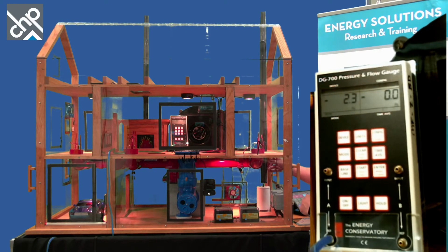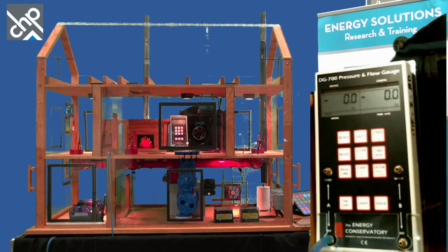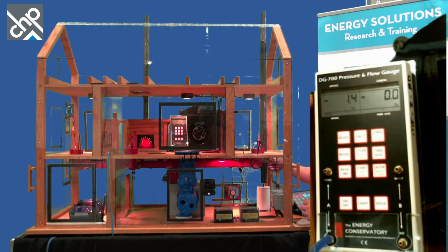Now I'm going to do it with the fireplace. I didn't have the fireplace on, but let's turn the fireplace on, and you'll be able to see these pressures from the smoke going up the chimney. So let's see what happens here. You see that the smoke is going up the chimney at this point, and I'm going to make that supply leak. We noticed it made a negative pressure, and we'll see if it affects the chimney. So I'm going to open up that same supply leak. Let's see if it makes a difference. Yeah, it actually pulled the smoke back down the chimney there. As soon as I put the leak back in, the pressure starts to equalize again, and now the smoke goes out.